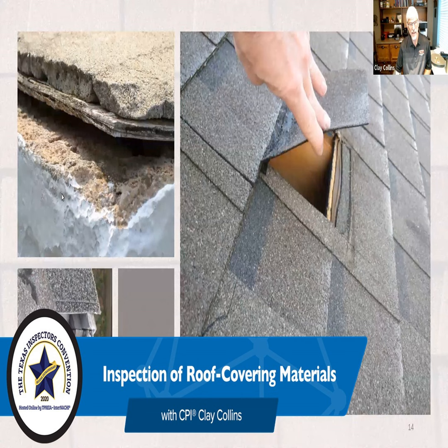Now the real risk here is you have a short width of decking, and the recommendation is that there are more H-clips than typically required. And the idea is to give more support there because this narrower piece is simply weaker along this area.